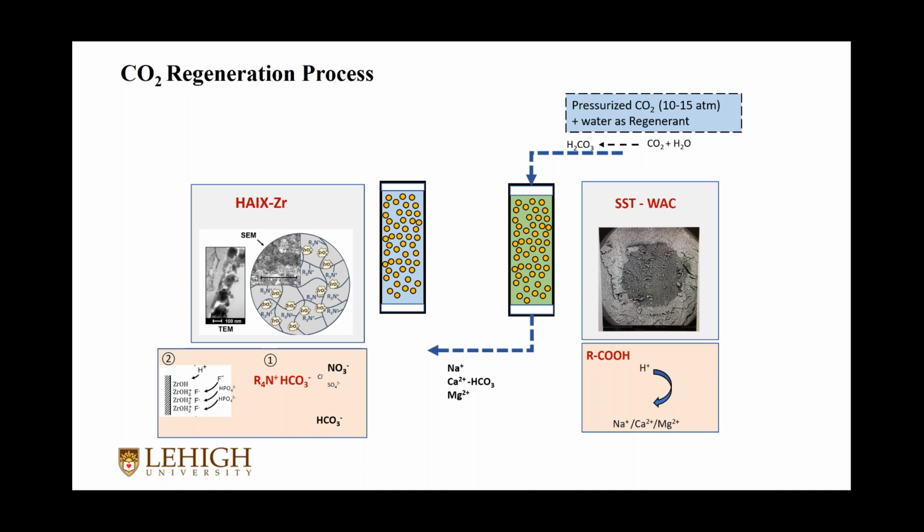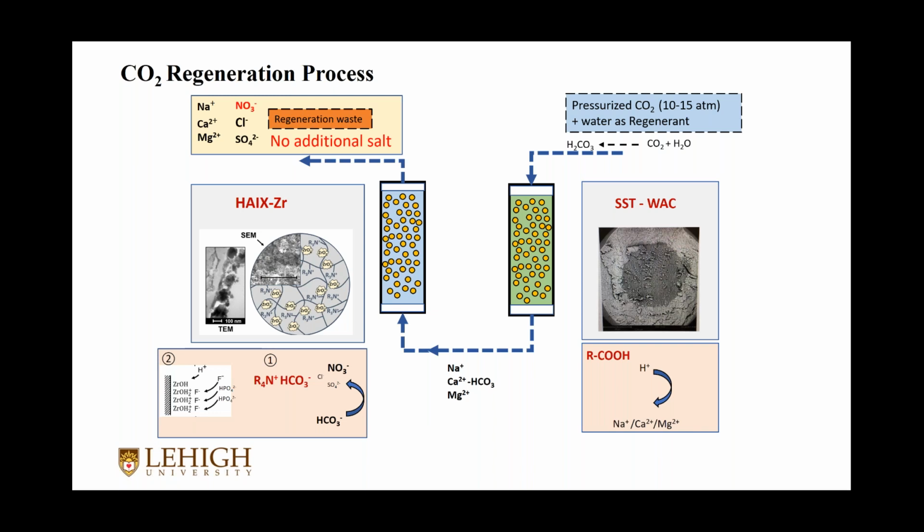After the second column, the effluent contains sodium bicarbonate and calcium bicarbonate, because all the hydrogen ion has gone to the resin again. This bicarbonate solution then goes to the first column to regenerate it, and also kicks out all the nitrate removed in the previous cycle. This finishes the whole process. We bring back both the cation and anion resins into the form we desired: cation resin in hydrogen form, anion exchanger with bicarbonate ion.